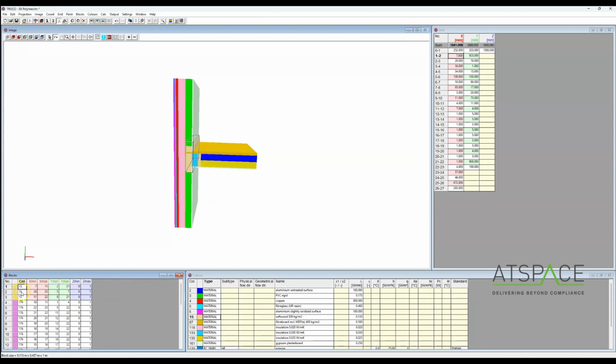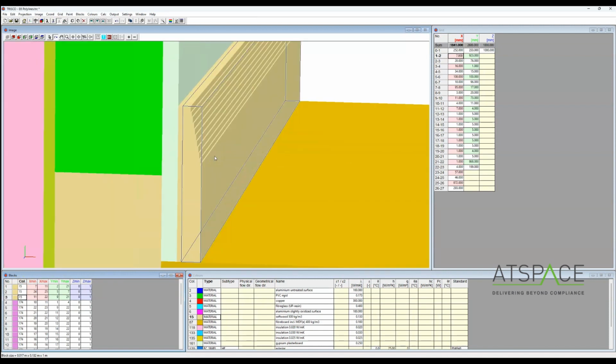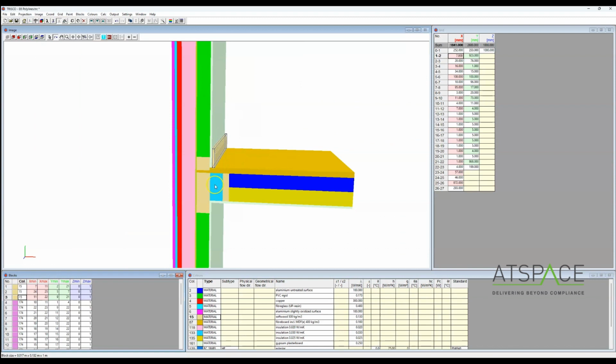Each of these blocks, when you click on the block, shows you on the main model which bit it's referring to. And you can see here the grid references that those blocks are occupying. Block number 2 here is color number 15, which is softwood, which is what we want. It's occupying the space between 24 and 25 on the x-axis.